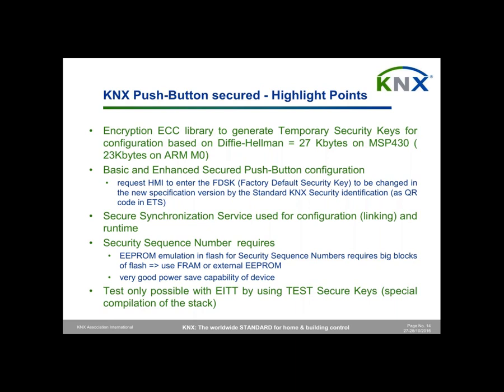One next big requirement for security is that you need to store the security sequence number in case you are losing power supply, or you make some updates. So for the ERL module, we have chosen to use an EEPROM emulation in Flash.